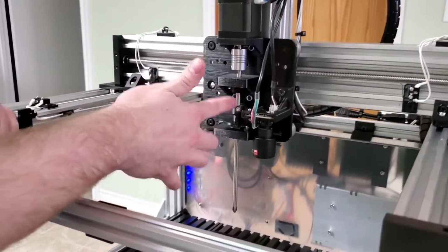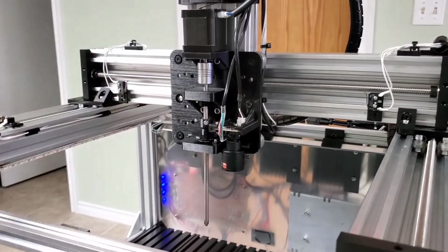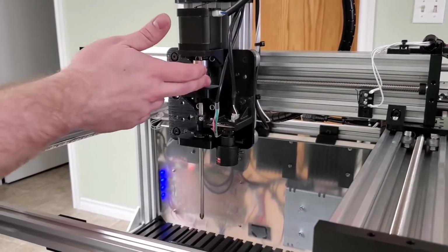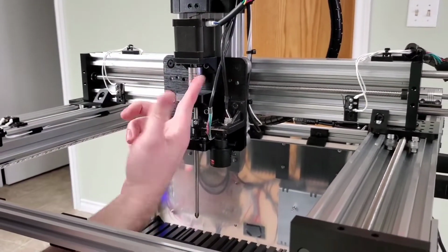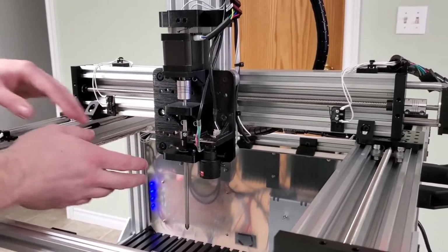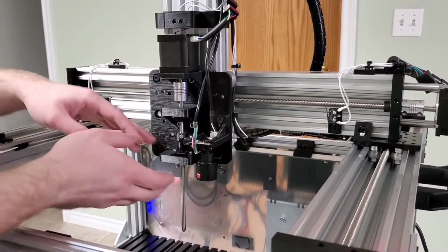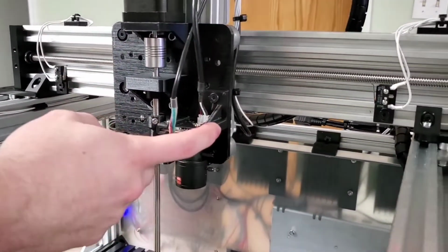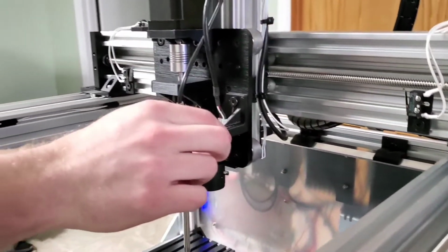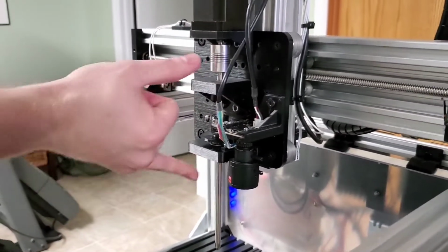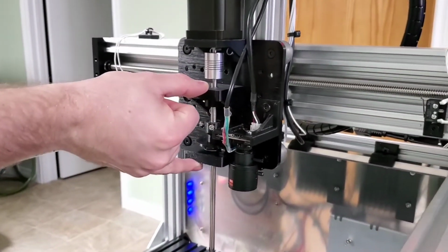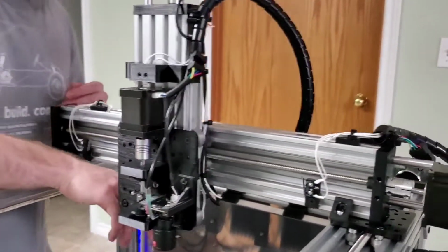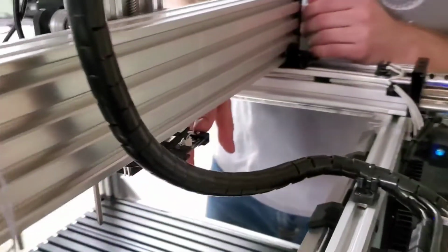And then on top of that, we have our screwdriver shaft. So this is a machine screwdriver shaft. This is about 15 centimeters long, combines into the flexible coupling, and then has a flat portion here to avoid slippage. On this, we mount our encoder, which Jared will further elaborate on. And then we have our optical sensor here. And of course, we have our zoom camera right here. So this is another custom bracket like this one as well, and this one and this one. These two brackets have bearings in them. They have 6mm bearings to ensure the straightness and the lack of slop. And then just on the back here, we have the rear camera, or our wide angle camera, what is used for mapping.